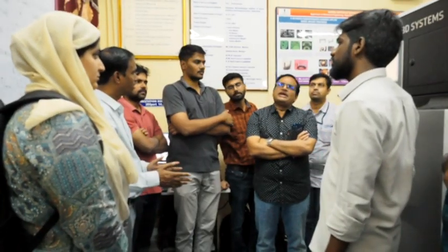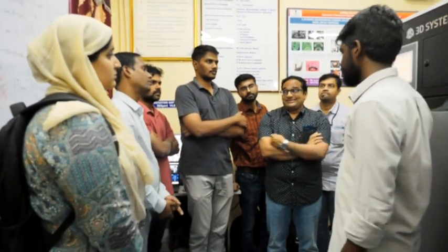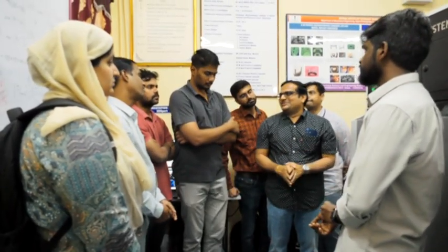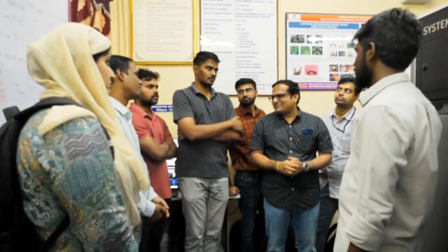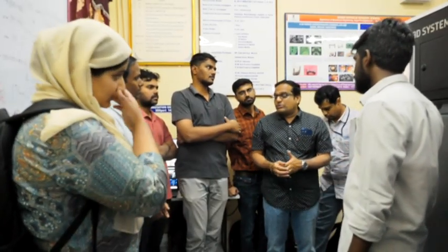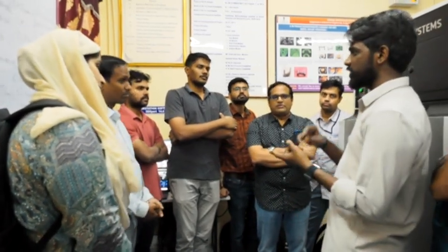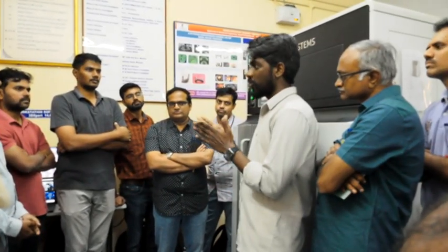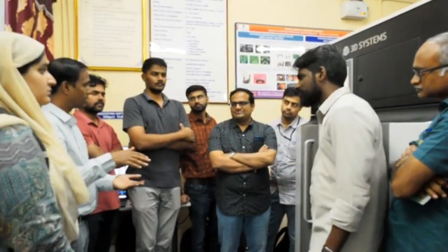But again, providing the support is also a difficult task, because you have to remove it. Removing supports in post processing takes more time. But we are not in a hurry to minimize or remove the supports, as that will lead to thermal problems. I can understand the supports; we need to put more effort during post processing. One solution is, instead of removing the supports, you give some lattice structures, which have high surface area to flow the heat. That's another solution.